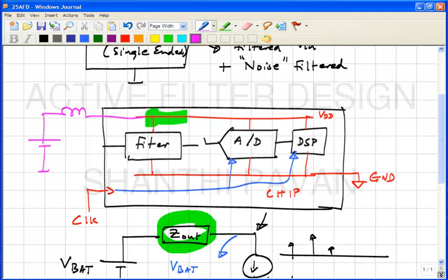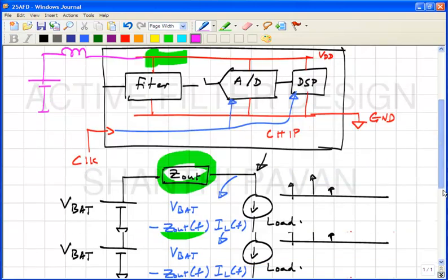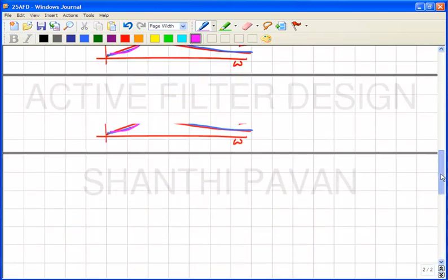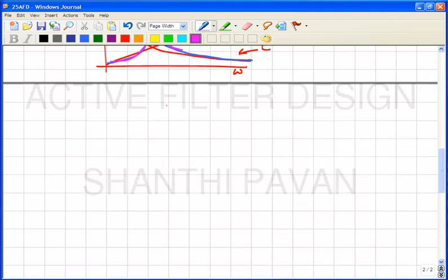Perhaps you route supply separately to the digital logic as well as to the analog part, and you join them together only outside. Now, this is digressing from the main theme, but I will just do it since I mention it. So, let us say this is the analog, right?